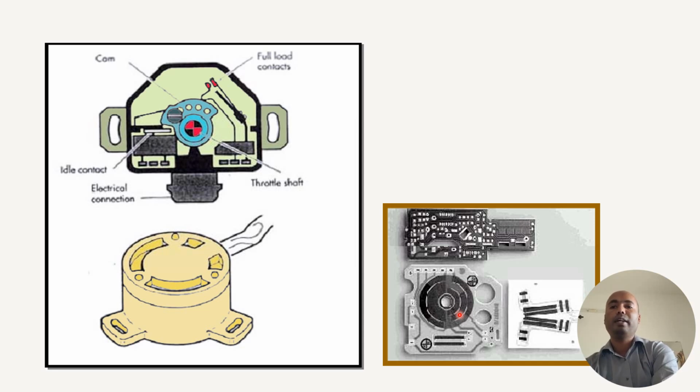Depending upon the resistance, these contact points are located at different resistance positions. For example, if the resistance value is 1 ohm, then 5 volt is given. Afterwards, depending on the resistance, we may get a 4 volt DC output. Based on this output signal, the ECU can easily recognize it. So the output must vary from 0.1 volt to 5 volt DC.